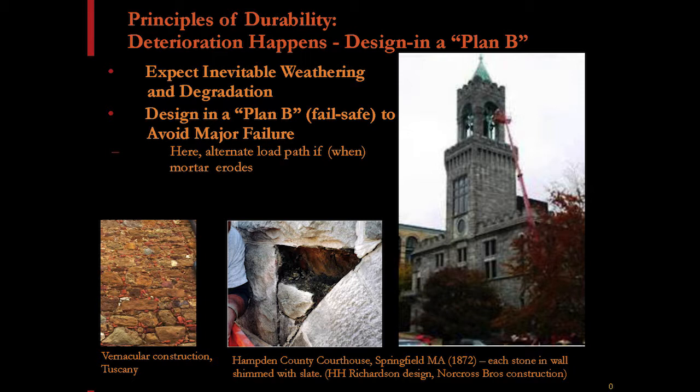It was basically just reverted to sand. And they shimmed every stone. In this case, they used slate to fit in there nicely and tighten up the joints and create point-to-point contact between the stones, so that when that mortar totally deteriorated, it was all pinned together